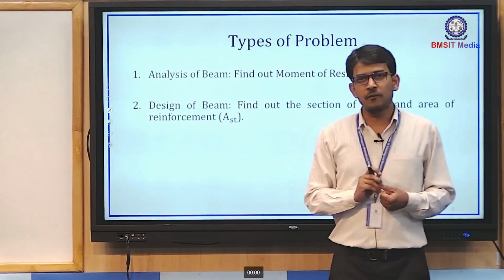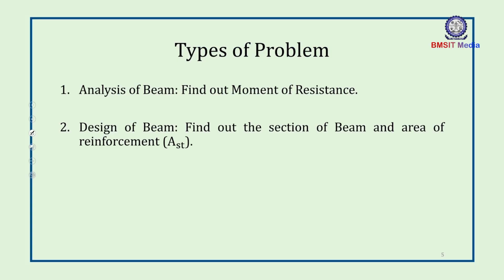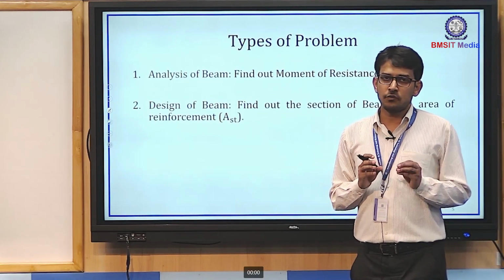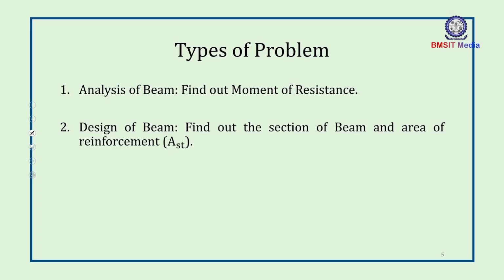So, analysis of the problem. The size of the beam is given to us, and how much reinforcement is provided, that we also already know. So we only have to calculate the moment of resistance. Such a type of problem is known as the analysis of the beam.